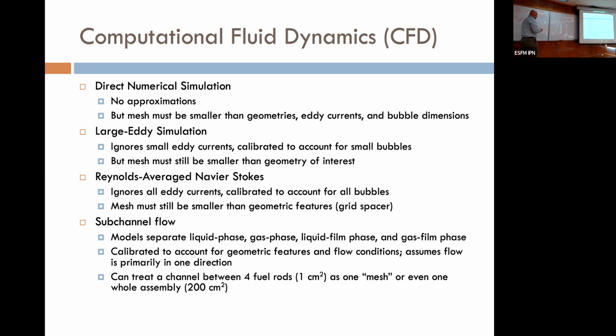And so you wind up saying, okay, let me put my mesh in here, and my mesh is starting to look like this to get that flow. And where these circles come together, when you have circles touching, you have to have really, really tiny mesh cells in there. And you wind up filling this problem with these mesh cells that are around these little knobs. And you say, that's too hard.